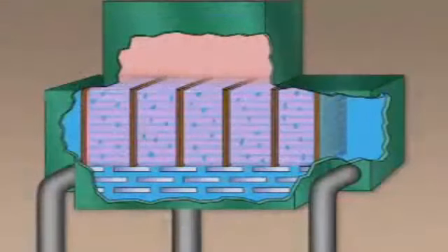Some circulating water systems also have connections to a water box priming system and a chemical injection system. The water box priming system removes air from the water boxes. This ensures that the circulating water tubes are always completely filled with water. If the tubes are kept completely filled, maximum heat transfer takes place in the condenser.